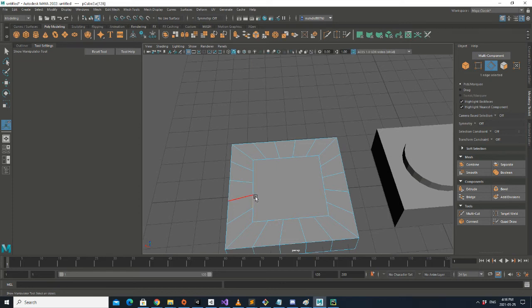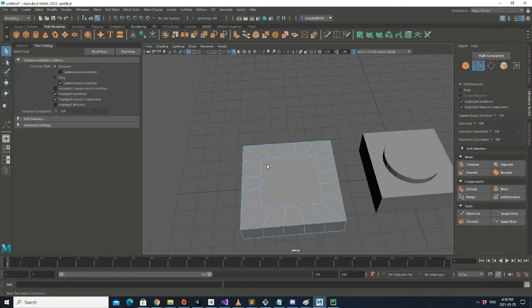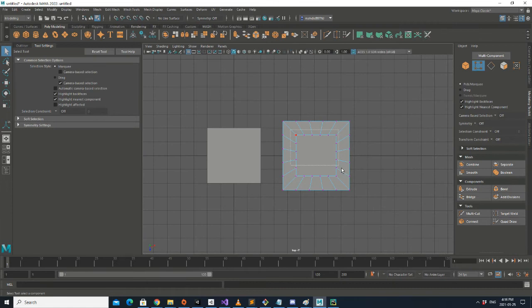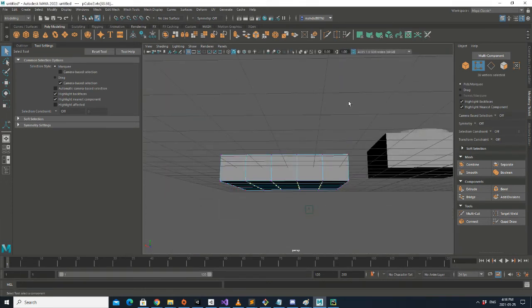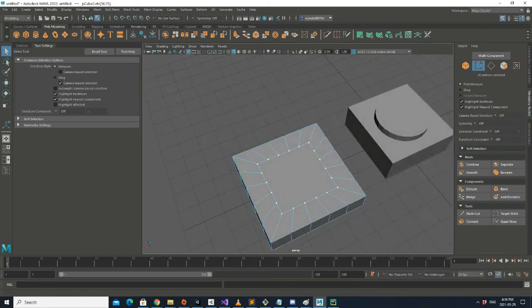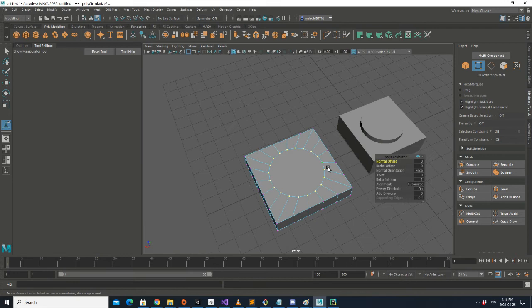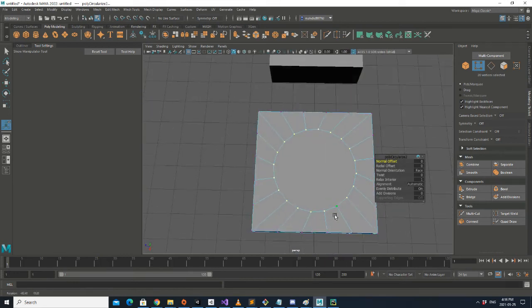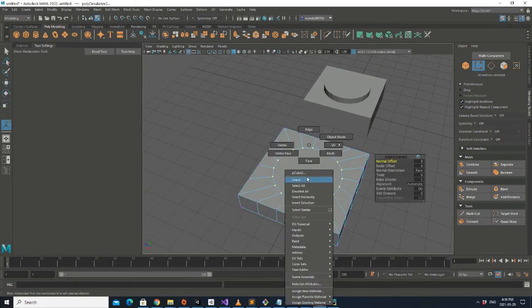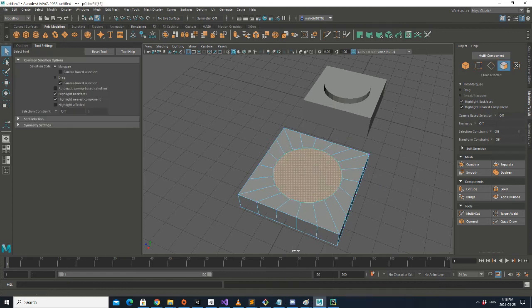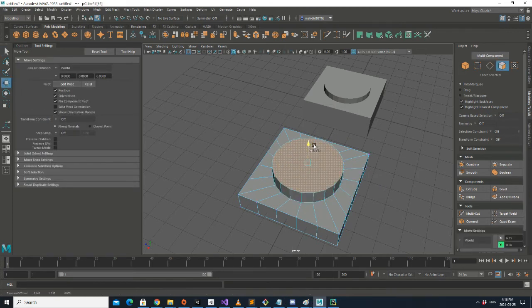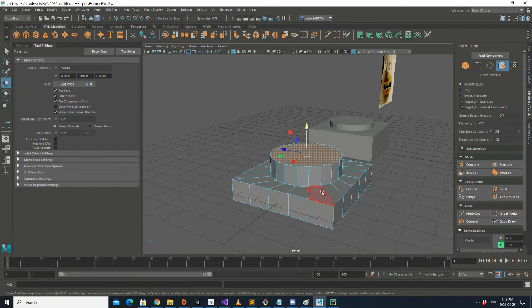Then select all the vertices from the top and deselect the ones from the bottom and go to circularize, where was that? Yeah, it's here. Circularize button and you will get your circle there. And now, that was a very long step, you can just extrude your cylinder out.